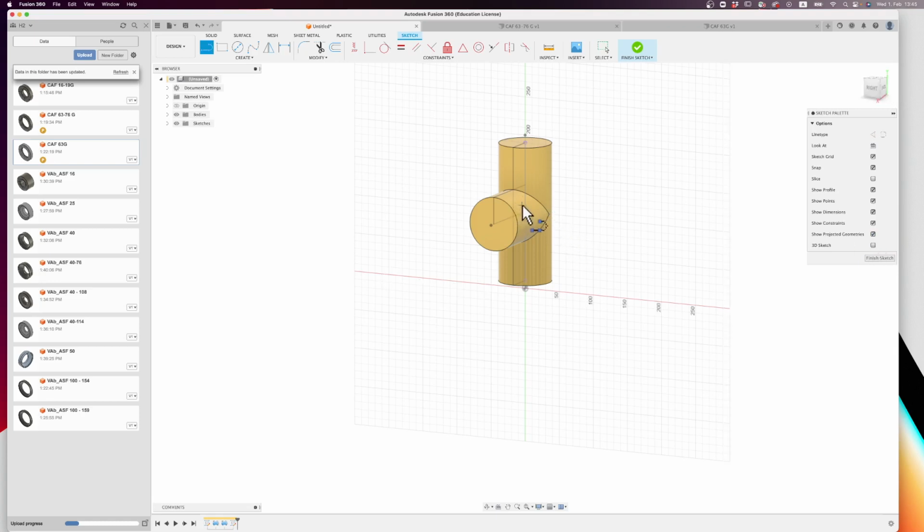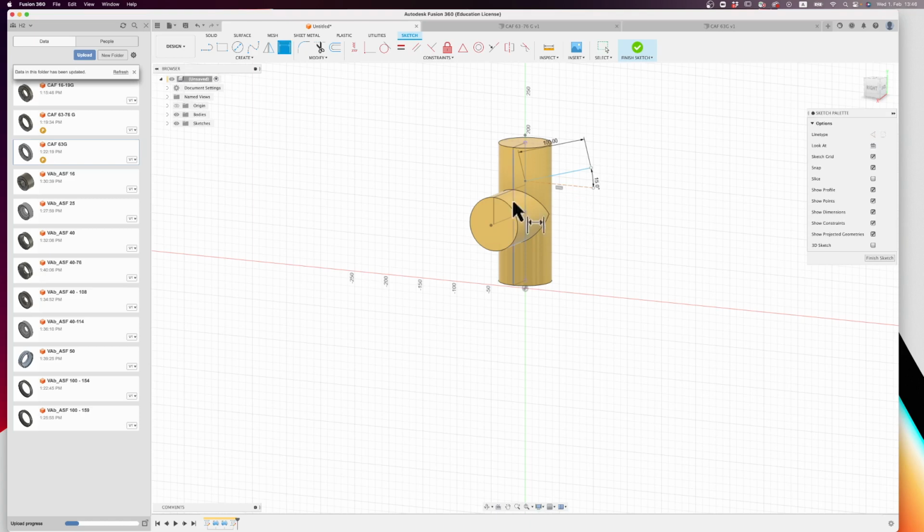And so here what I can say is I want somewhere on this line, I want this to be up by 45 degrees or by maybe just by 15 degrees so that we don't run into any problems. Anyway, so we can say, okay, we want this to be also 100 millimeters and this to be 15 degrees. So I set odd angles. And the next thing we're going to do is define the offset here and make it maybe 30 millimeters.